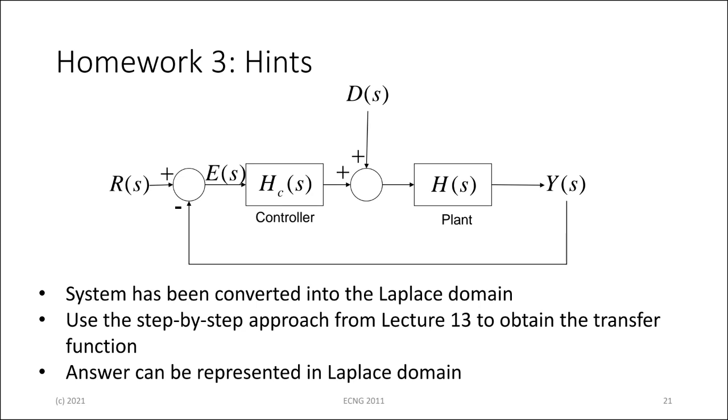Moving the blocks around and shifting them around is conceptually fairly simple, once you remember the four things that we spoke about: moving a takeoff point before and after a block, and moving a summing junction before and after a block. You cannot swap takeoff points and summing junctions.